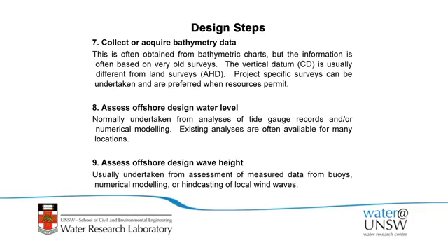So on to another design step. Collect or acquire bathymetry data. That's a bit harder to get. It's often obtained from bathymetric charts, but the information on those is often from very old surveys. Certainly even today, for some of the mid-north coast of New South Wales, the bathymetric charts, if you read the fine print, were acquired about the 1850s or thereabouts, believe it or not. So best practice would be to go out and collect it specifically for your project. Usually there's not enough funds to do that, but certainly that's best practice.